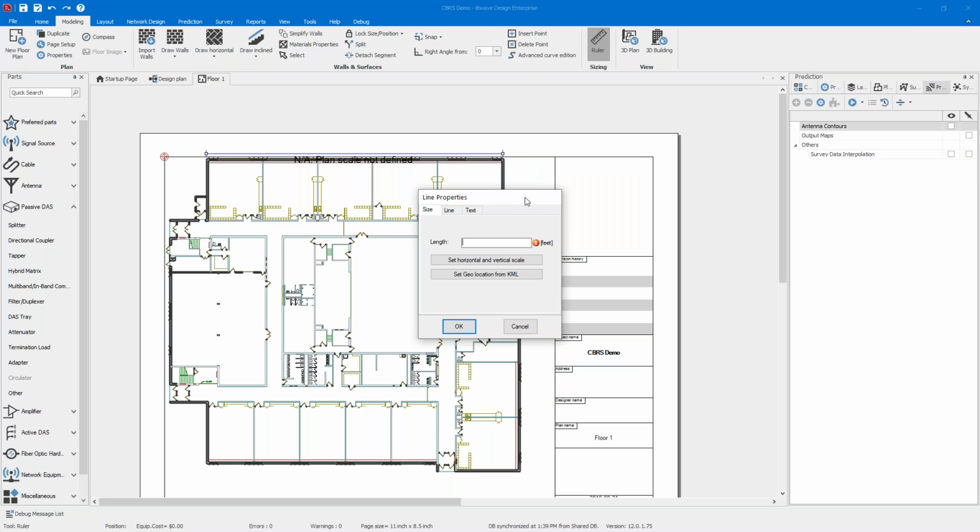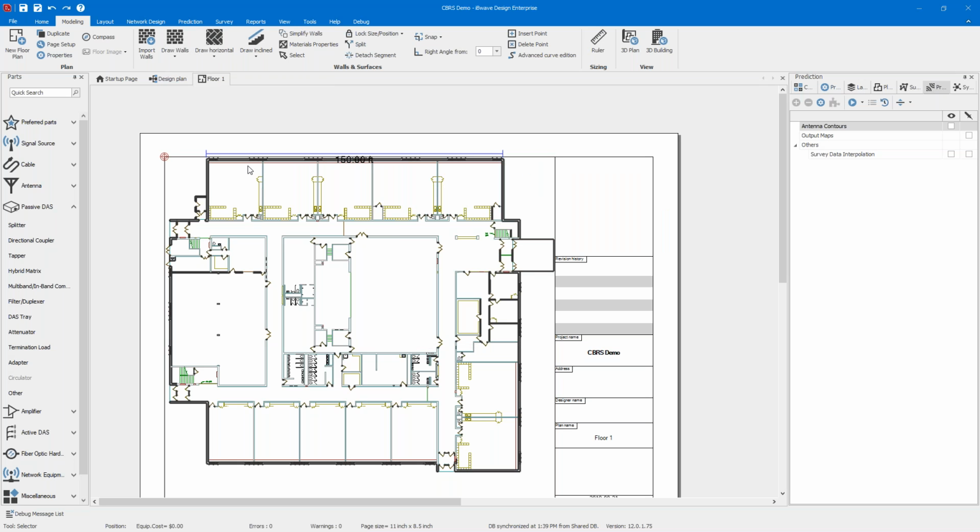And let's say this is 150 feet. And then if I don't have a CAD drawing, I have the drawing tool here. I could draw any walls I want or any inclined surface, and I could also draw horizontal surface. This will serve as my ground floor, and it will also serve as the ceiling for the floor below. So it will be taken in consideration for the reflection on the floor and then the loss between floors.